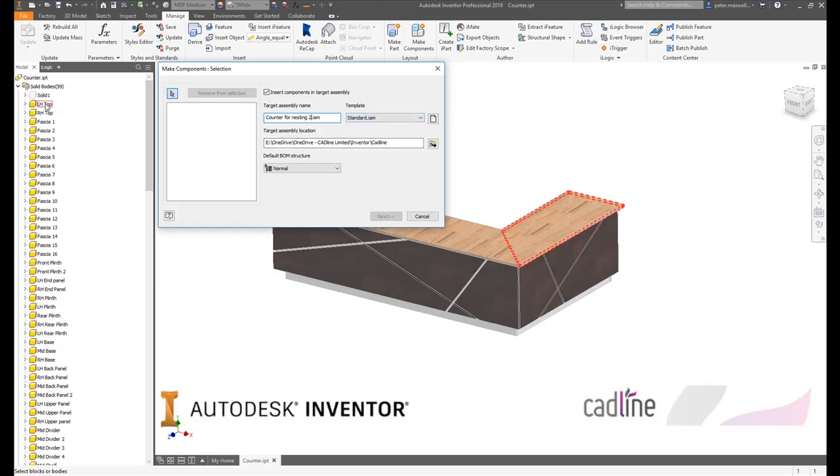From there we can select the solids that we want to take across, and you see here I stopped at front plinth 2, because essentially this part and this part here are the same, or going to be the same parts. Now if I take this solid across, it will show it, but it will also make it as its own individual part, and that wouldn't be correct for our bill of materials.